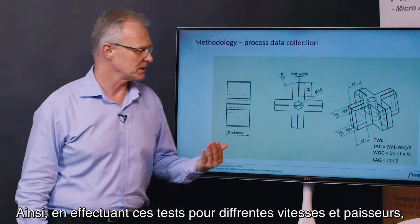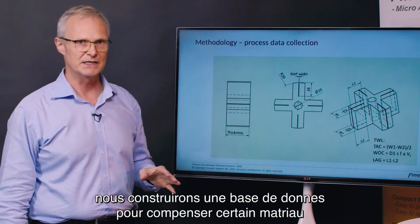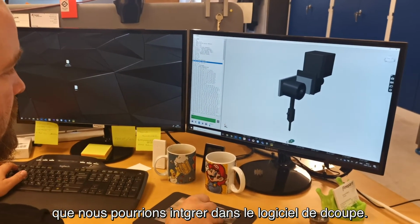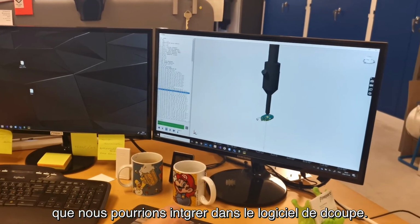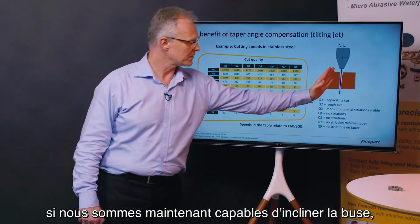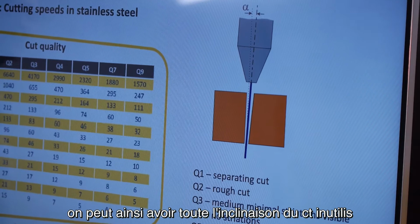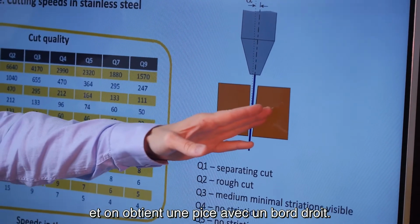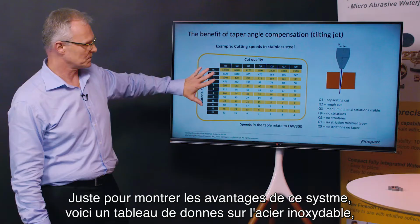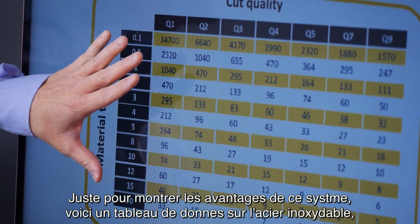So by doing these tests for a number of speeds and thicknesses, we will build a database to compensate for the certain material that we can build into the CAD/CAM system. The benefit of taper angle compensation would be that if we are able now to tilt the nozzle, then we can get all of the taper on the scrap side, and we get one part that would have a straight edge.